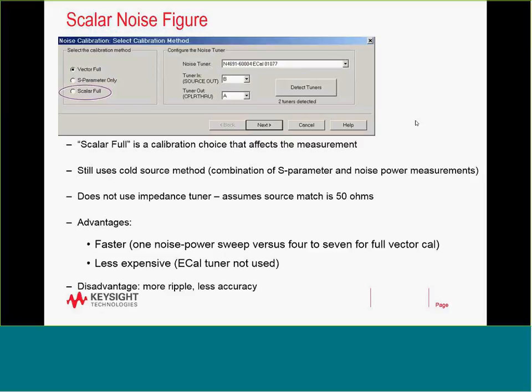And the other technique more closely represents a noise figure measurement made by the Y-factor method. Okay. Because the Y-factor method does not report the noise figure at 50 ohm impedance, but at the impedance of the system. Okay. So the scalar portion of the PNA is more representative of system noise figure and could be related a little bit closer to the Y-factor method using the spectrum analyzers.